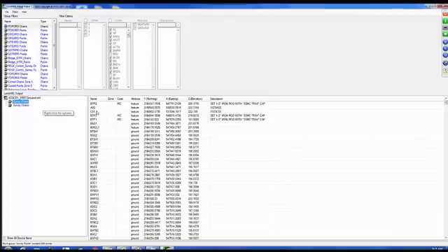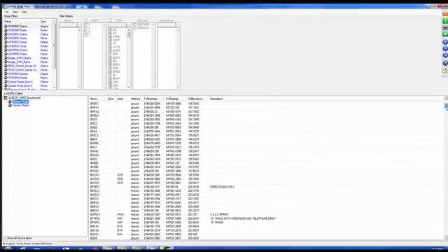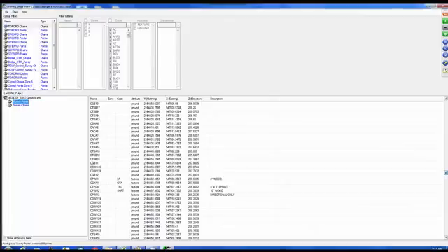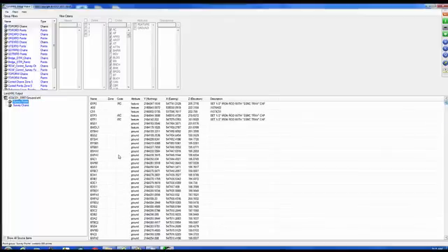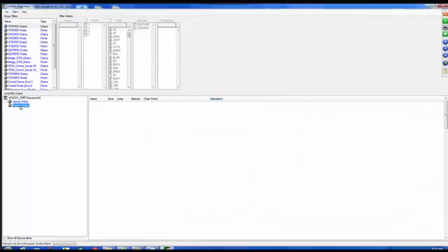Okay, well, on this particular set of points that I brought in, you'll notice that under zone, there are not any points. And we'll talk about why this is important. So we don't have any zone codes in this particular point file. Okay, so we do have some codes. We have an attribute, whether it's a feature or ground, or northing or easting or elevation, and then we have some descriptions. Let's look at survey chains.